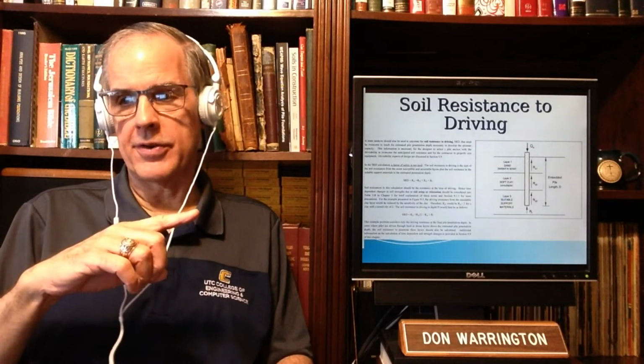One important, again, and I kind of mentioned this before, these are kind of a review. Soil resistance to driving is an important concept. And many times, the driving resistance of the soil and the soil you actually have is not the same. In this particular example, there are a couple of reasons. One of them is scour.